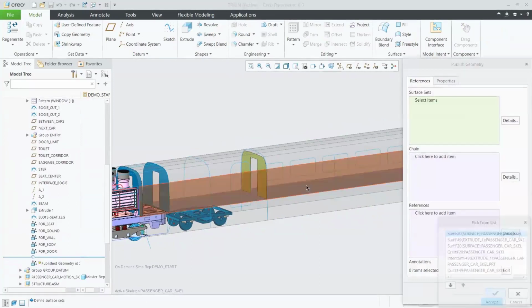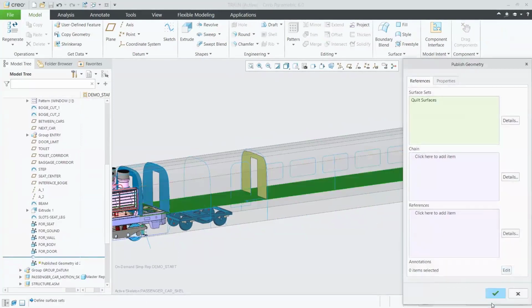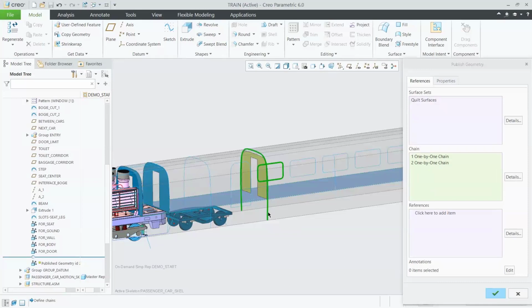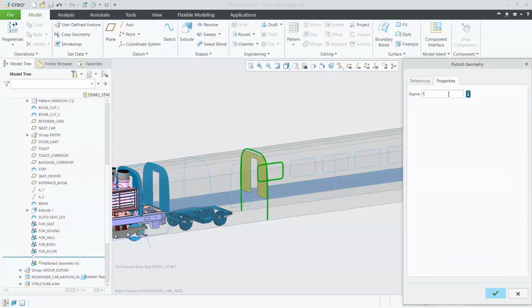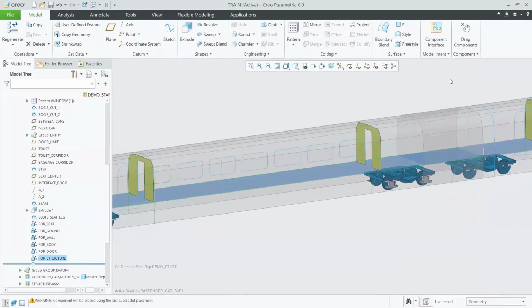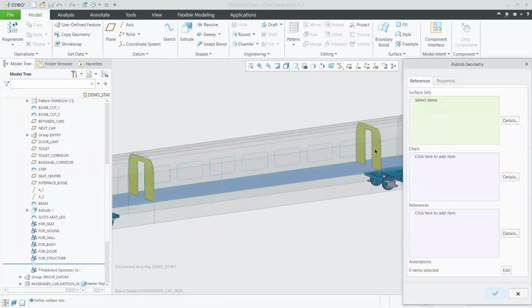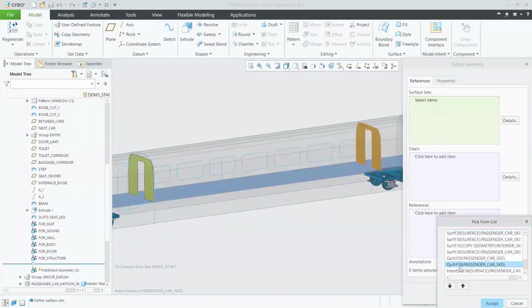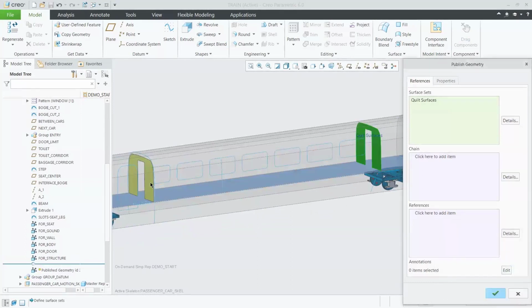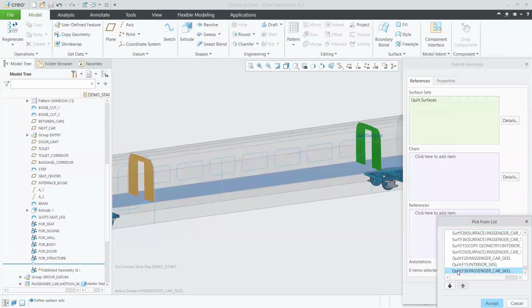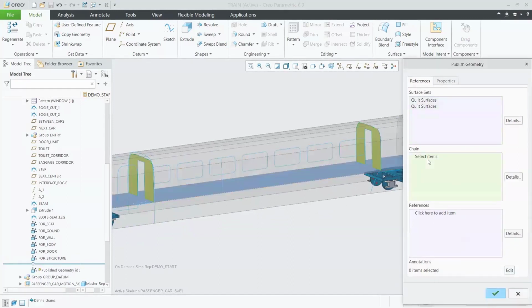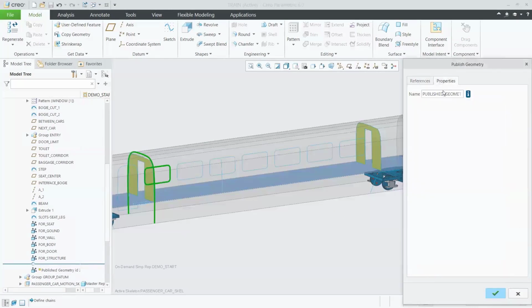First of all, like I mentioned, it revolves around the idea of a skeleton model. Skeleton model can be different lines, arcs, curved surfaces, anything that you want to use to set the overall control for that model. And the idea is once you have the skeleton model, I can say, okay, take these certain surfaces, take these curves, and I'm going to publish them and use them for particular purposes, maybe for structural components, maybe from that same skeleton model, we want to make another set of published geometry for our internal surfaces. So maybe we'll grab a surface over here. Let's go ahead and get one for the window here, some of our different internal components that we have there. And we're going to publish this out, and these are going to be for our interior components.